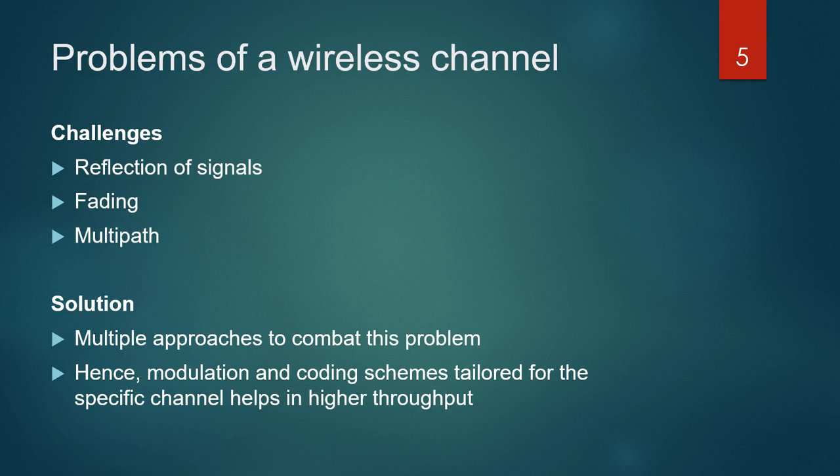There are multiple problems that can be listed for a wireless communication system. A typical wireless communication channel causes delays in the signal components and also causes reflection of signals, which results in the receiver getting multipath signal components that tend to affect each other randomly. The outcome of this is the fading and attenuation of the signal. This gives the receiver a high probability of decoding erroneous data, leading to lower throughput. Channel fading has always been a problem and has been in the spotlight for many decades.